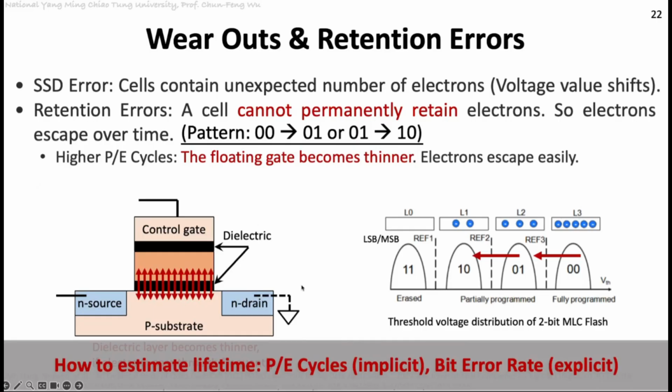Each time we read data from the SSD, from the NAND cells, we can check their bit error rate and know the exact status now. Is it close to error-prone, or is there not that much error now? If you read out the data and find this cell has more errors, it means this cell is going to be worn out soon. And if the bit error rate is super low, that means this cell is super healthy.